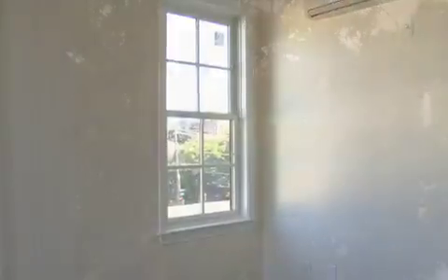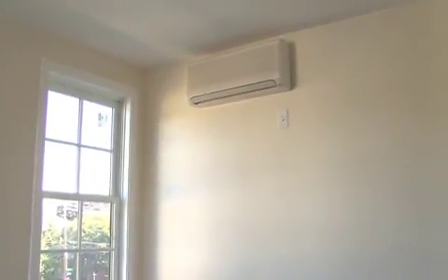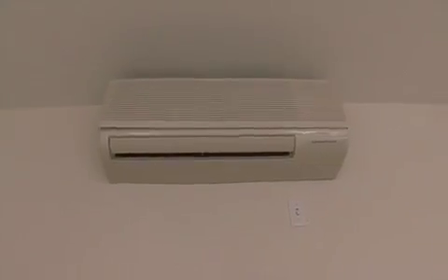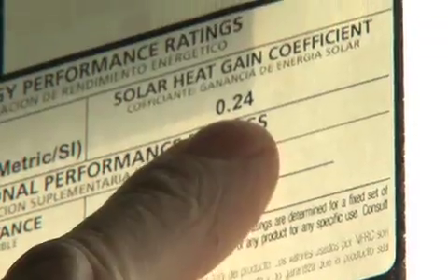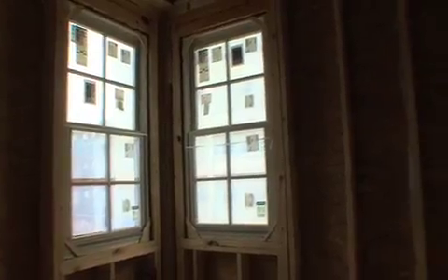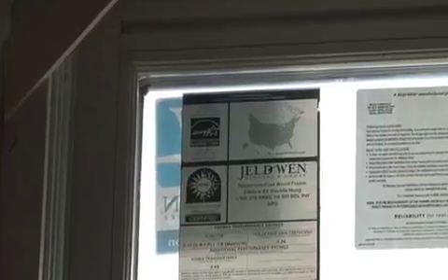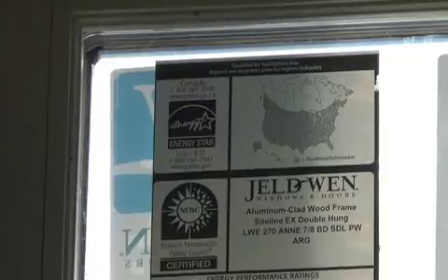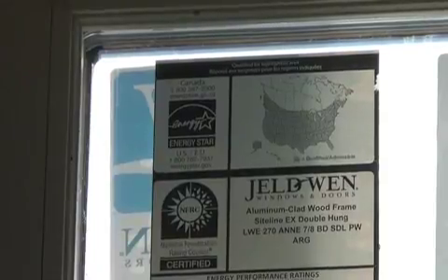However, solar heat gain from window glass is often the reason many buildings require air conditioning. This number over here is solar heat gain coefficient. That basically tells you how much of the solar radiation that's hitting this window gets in. The low solar heat gain coefficient cuts down on solar gain when you don't want it, which is in the summertime when you're air conditioning.